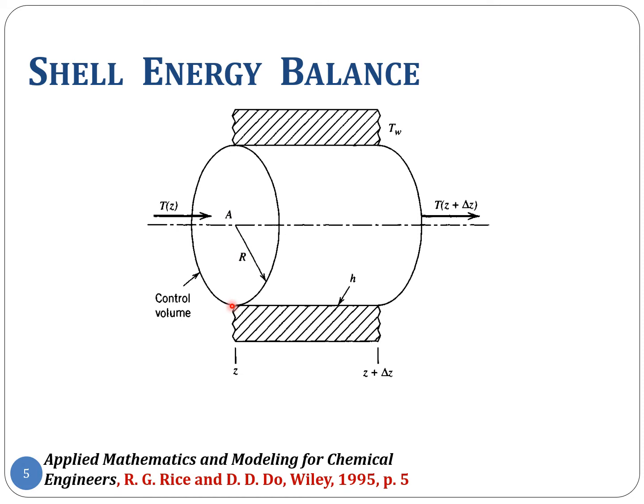So temperature is constant at any cross section, which means the entire contents of this cross section are so perfectly mixed that everywhere from the wall to the center, the temperature is uniform, right? And the momentum is also uniform, and therefore the fluid has a constant velocity everywhere in this cross section, which we know from our momentum transport discussions is not exactly correct. There should be a velocity profile because there is friction here which should result in no slip, and here there is minimal friction and there should be maximum velocity, right?